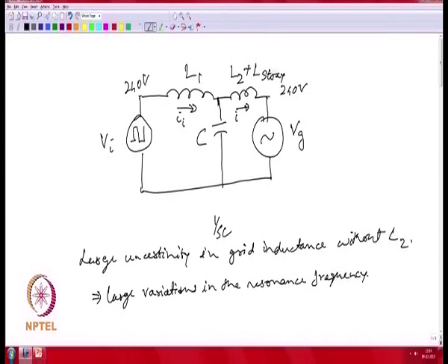The voltage across the capacitor would be actually close to 240 volts. So, we are talking of approximate value of the voltage in the filter network. So, there is actually reactive power which is being drawn by the filter capacitor, and you do not want that reactive power to be excessive. So, that would actually form another constraint on the filter design.